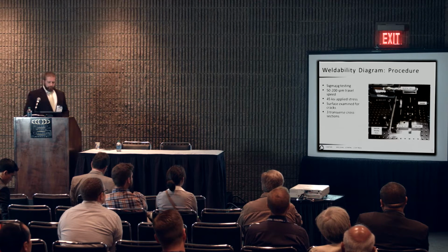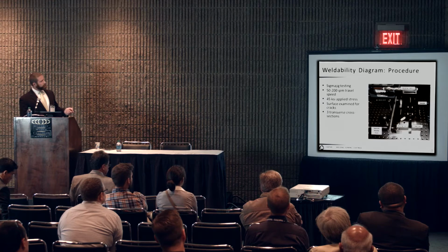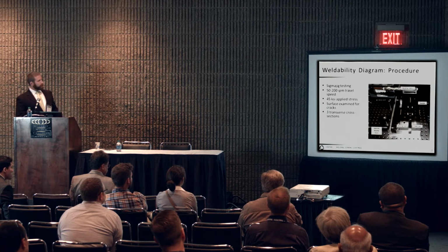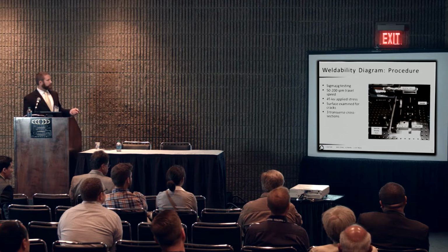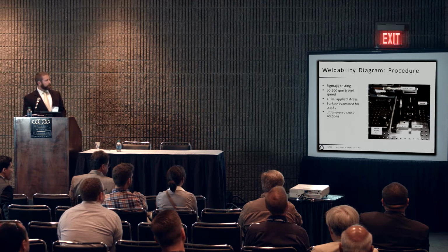So the weldability testing we used is all sigma jig testing with an IPG fiber laser power source. Here's a sigma jig fixture here, fixed jaw, our sample in the middle, and then our moving jaw. The moving jaw is preloaded with a stack of Belleville washers and puts a known preloaded tensile stress on the sample. In this case, all testing was done at 45 KSI. And then put an autogenous weld across the sample, and then examine the surface for cracks as well as the transverse cross sections to look for subsurface cracking.